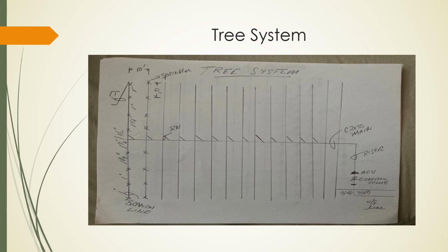You can see that in the upper left-hand corner, and right next to that, those cross marks are actually sprinkler lines, and they're also sprinkler heads, and they're changes in pipe size in some cases, or sprinkler head placement. And so in this case, it's 12-foot on center spacing between heads.